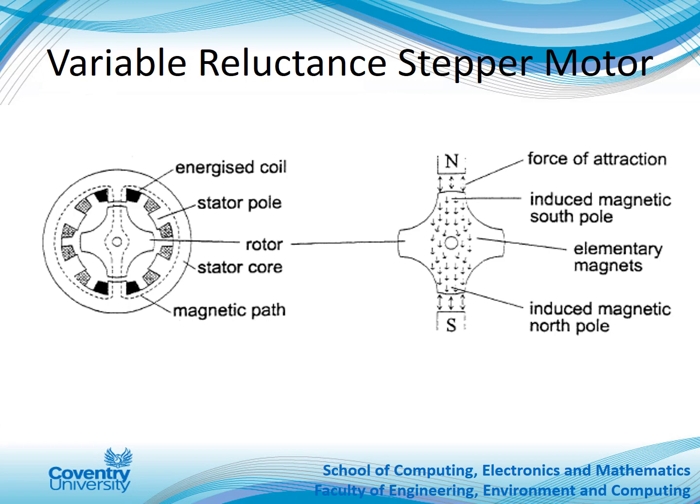Some stepper motors allow half steps, and some even allow a finer microstepping process where you can vary the voltage on each coil, which allows you to go to actual fractions of a degree. They're extremely useful in astrophysics, where you want to shape the parabolic mirror of a telescope to fit your application, because you can't make them out of big pieces of glass anymore because they warp. So mounting bits of glass on stepper motors allows you to change parabolic mirror curves, and that's one application of stepper motors.